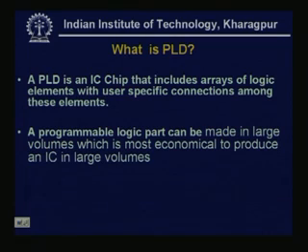So, a PLD is an IC chip, we think, that includes arrays of logic elements with user specific connections among these elements. Normally it has two different arrays, and they can be programmed from outside. Now, we will see later how these arrays are programmed, what the structure of this array is, and why it is so popular, or what the advantage is.